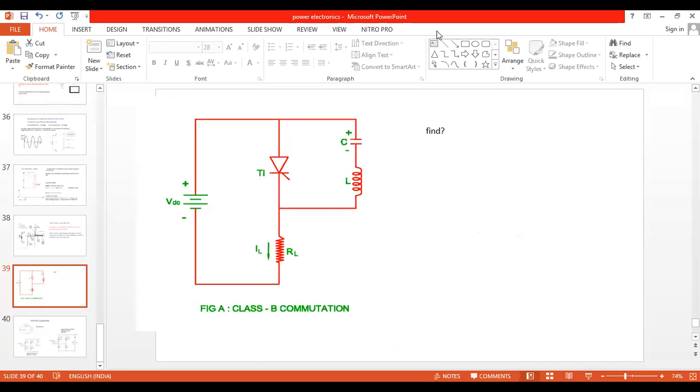Okay, so I'm just putting out here, all of you. If anybody can explain, explain me. What is mode 1? Always mode 1 is how to turn on the SCR. Tell me, when the supply is on, current flows from VDC plus to where? It will flow through the SCR. We are giving firing pulse to SCR. SCR is on. Current flows through the load, from load to the negative terminal.